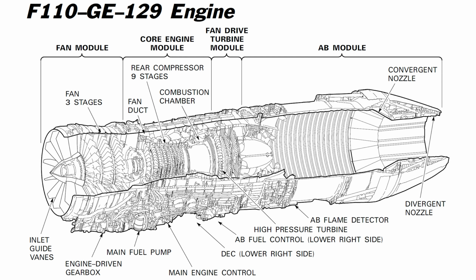The aircraft is powered by a single F110-GE-129 afterburning turbofan engine, producing approximately 29,500 pounds of thrust. The control system is composed of 3 major components: the digital electronic control, the afterburner fuel control, and the main engine control. The DEC is an engine-mounted, fuel-cooled, solid-state digital computer and is the critical component of the primary engine control. It controls the main engine and the afterburner.